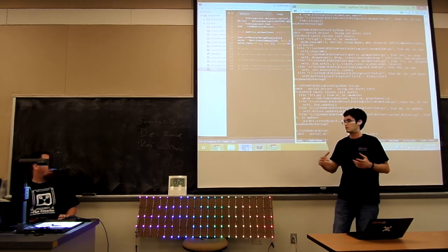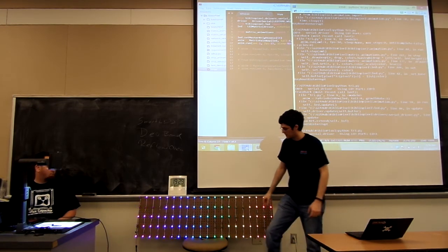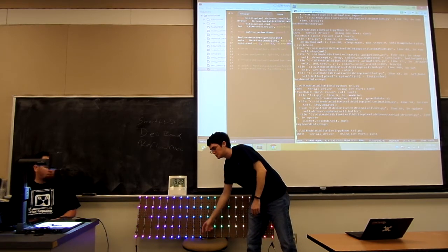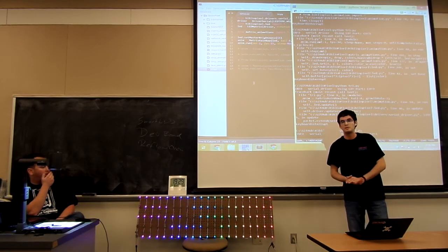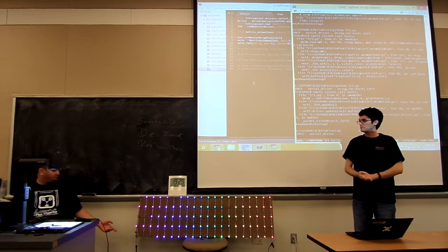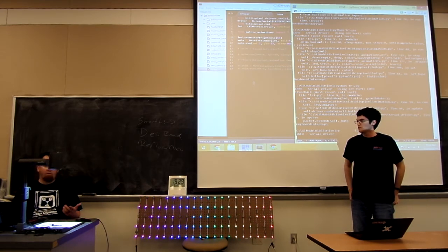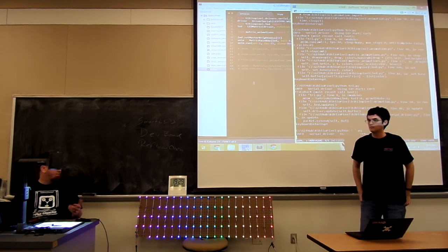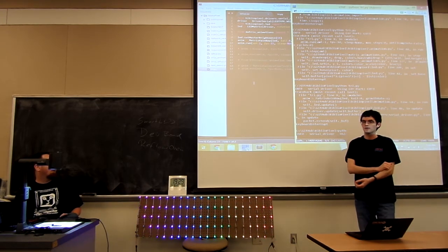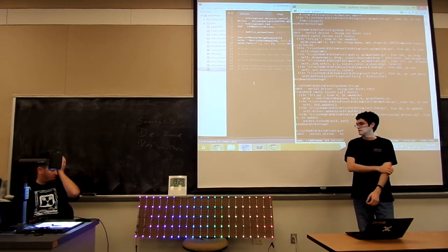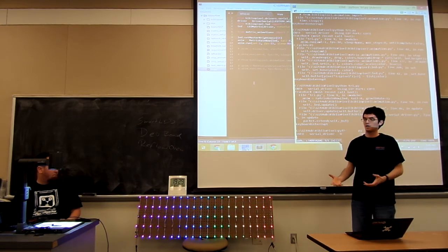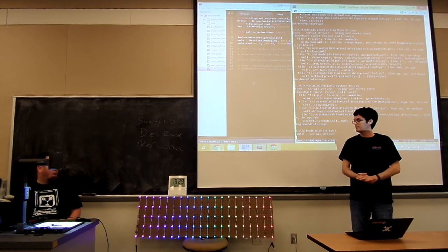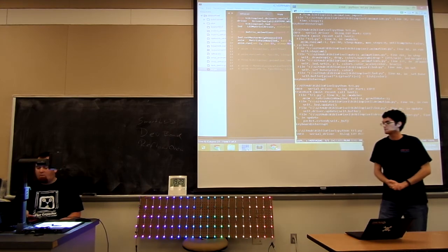So what you would do, if you really wanted to get that to work, is splice in another power tap right here to provide more power to the rest of the screen. Yeah, so like you see on this one, we've actually got power at both ends, just running from either side. And you can do it in the middle. That's all dependent on how dense your LEDs are, how bright you have them running, what animation you're running. Obviously, certain animations will draw more power based on the color that you're showing.